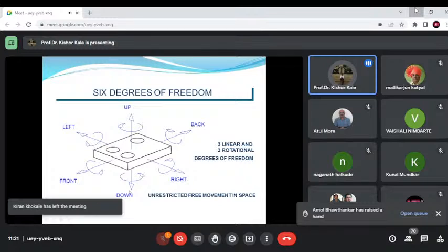Okay, so CMMs come in many different shapes and sizes with varying levels of accuracy. CMMs are used to take precise measurements of mechanical parts. CMMs can accurately measure features that would otherwise be difficult to characterize. Proper use of CMM requires understanding of GD&T. That's why I was talking about it. That's why GD&T was important. That's why I went through the minimum basic types of GD&T.